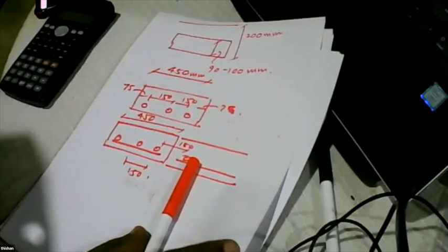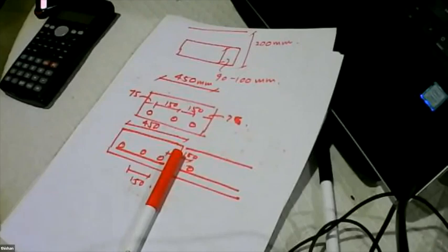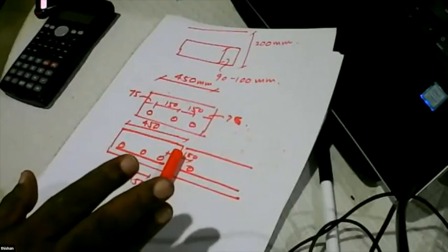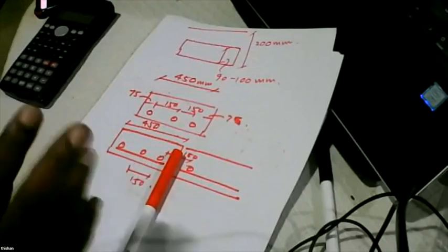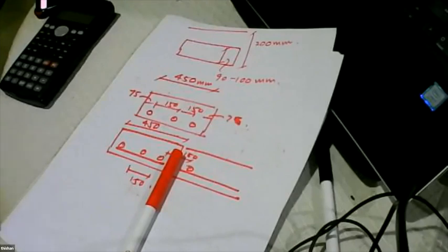Other than that, there's no specific reason, but don't try to have a huge spacing for the precast beams, because we are going to place the precast panels on them. When you keep the precast panels on the existing beam, we have to think about the weight of the panel if we don't have a crane.